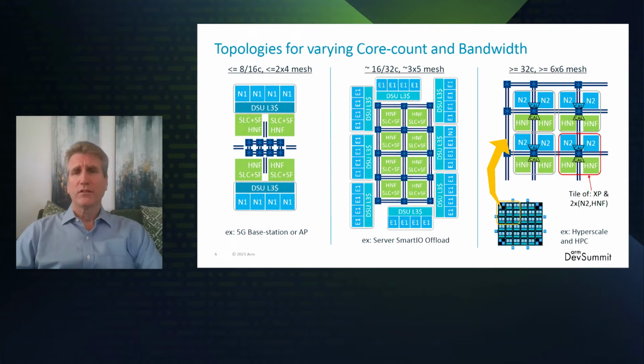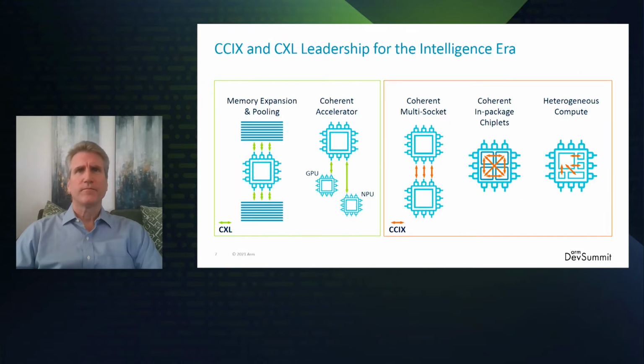Lastly, there are larger configurations and higher core configurations. We'll be advising grouping the CPUs and home nodes around a cross point as a tile. Then these CPU H&F tile templates can be replicated with parameterized signals and duplicated for a larger mesh, as shown on the example for the AWS picture below. Memory and I/O should also still be placed symmetrically around that mesh to provide good balance and distribution of cache memory request and response times to minimize congestion.